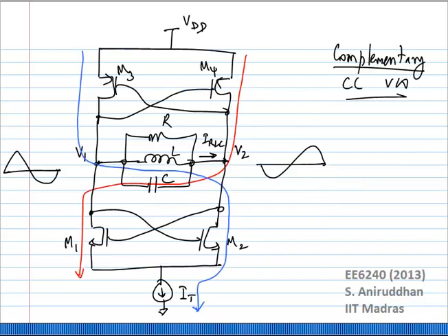If you look at the complementary cross-coupled oscillator, the way the current flows is slightly different, right? That much should be pretty obvious, because in this case, current is flowing through the complete RLC tank during both halves of the cycle. That is the difference between the NMOS only and the complementary oscillator.